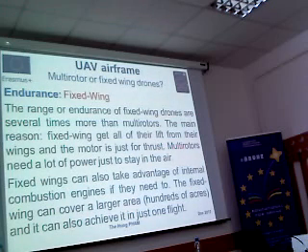However, multi-rotors need a lot of power just to generate the thrust to maintain the drone in the air. So, for the endurance, the fixed wing is the best choice, not the multi-rotors.